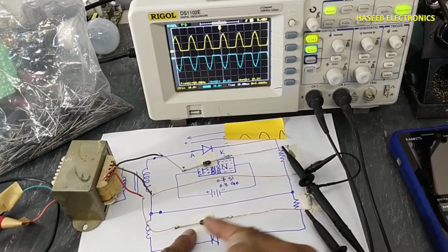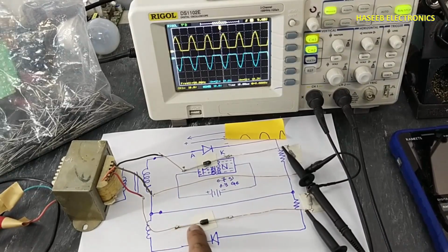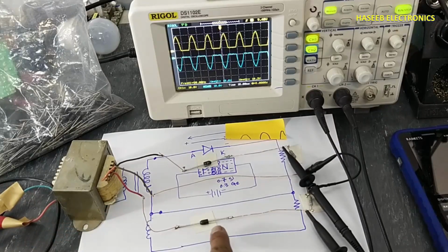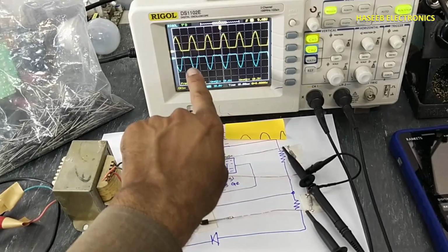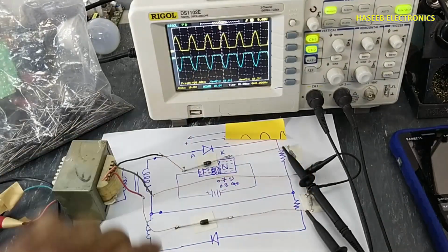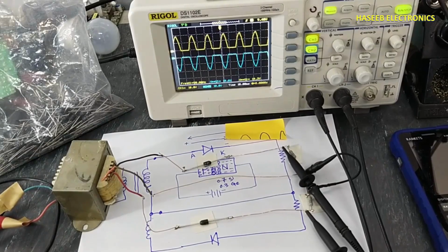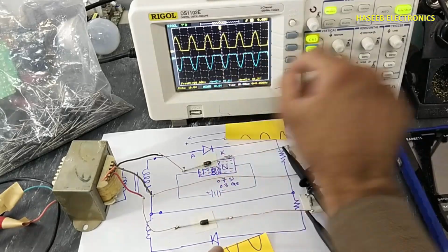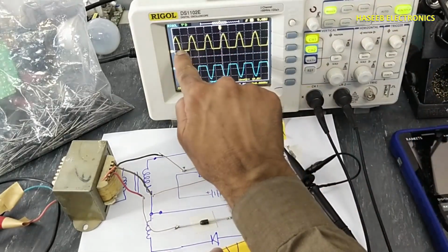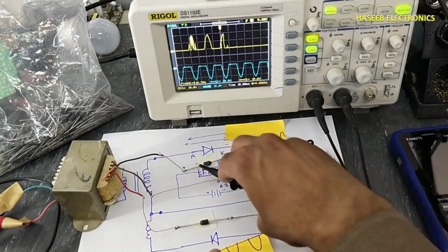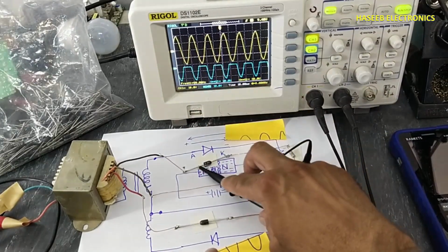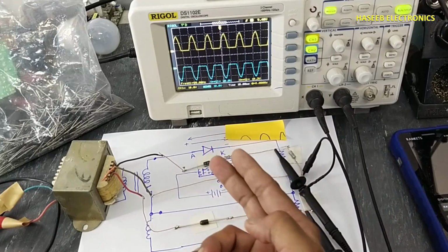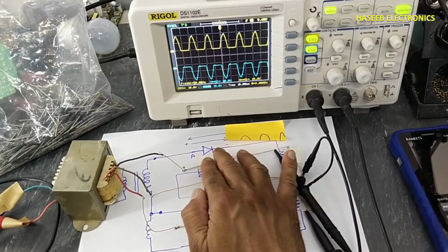When the diode is connected in this direction, with the cathode connected to the transformer or any AC voltage, and the anode connected to the load, at that time it will clip the positive peak and we will receive these negative peaks. Here it is clipping the negative peak, that is in this area, this peak, and it will drop this negative peak here, because in reverse bias condition it will block the voltage.